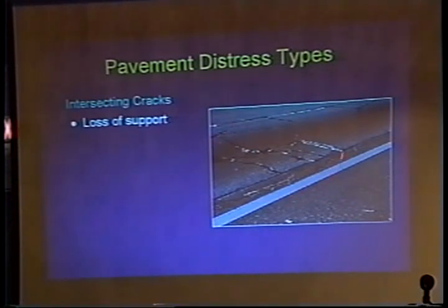This severe of a crack right in through here, where it just propagates out, is typically where they have a lot of intersecting cracks. You have a lot of different stresses from different directions. It's typically because of loss of support. That could also be, like I said, some of the other pictures up here will show you examples of loss of support and what to look for.